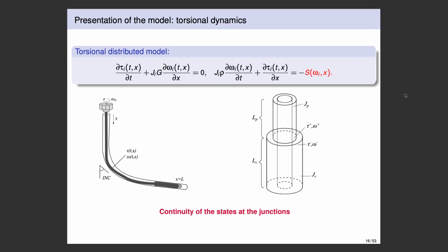So you have pointed to one source of torsional oscillations, which is linked to the transition from static to kinetic friction. But there is another source, which is the coupling between axial and torsional when you are off bottom. You can see from downhole measurements, when you are reaming up or reaming down, that torsional oscillation starts at the moment you change direction. Especially when you are reaming down, you can go into full stick-slip. That's a side effect of hydraulics, the surge pressure, which interacts with the rest of the string.